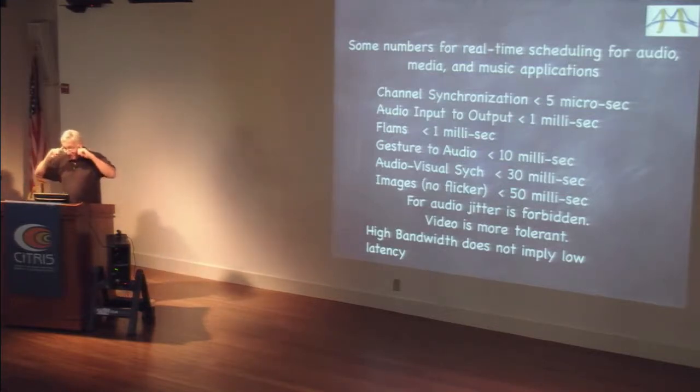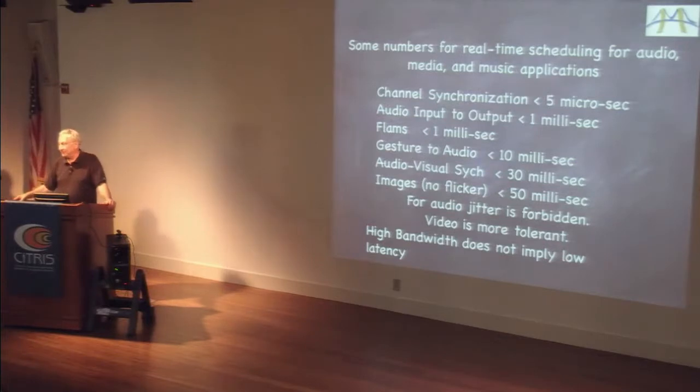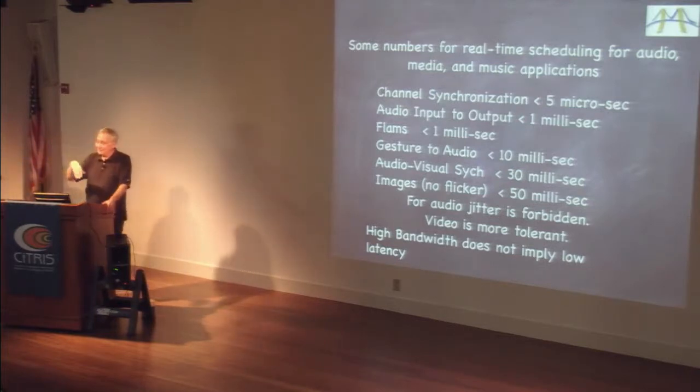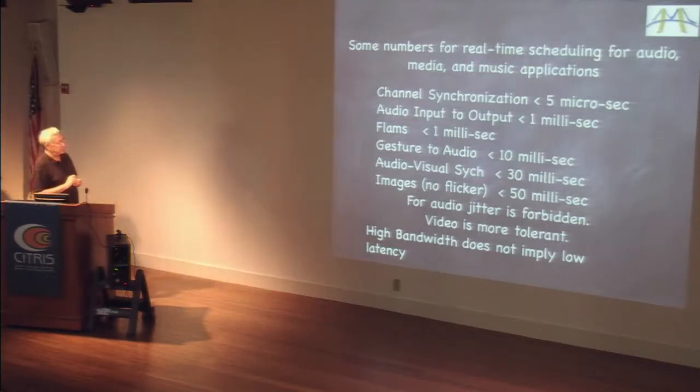If you think about the distance between the 2 ears and the speed of sound, well, let's say we're about 6.5 inches between the 2 ears, and now we're looking at our ability to localize in the front. We're accurate to about 3 degrees in many experiments that can demonstrate that. When you run that down, that's down in the sub 10 microsecond range. So that level of synchronization is important.